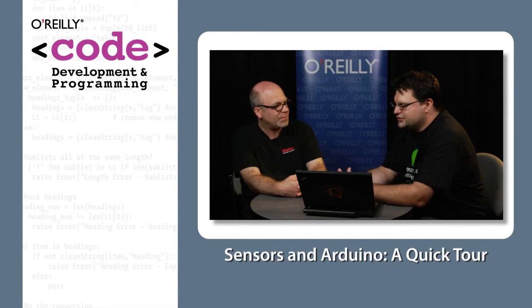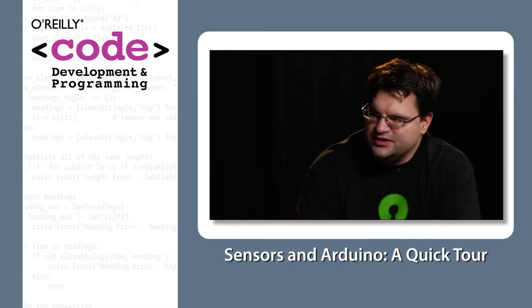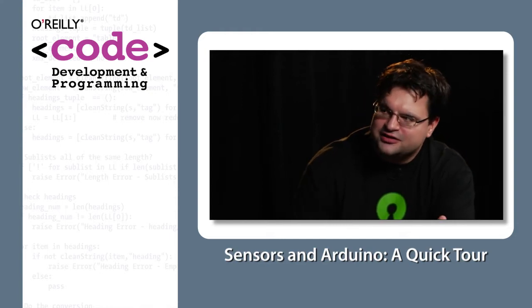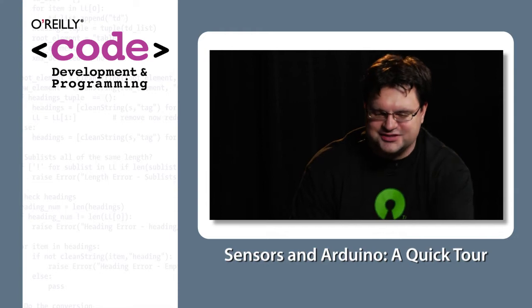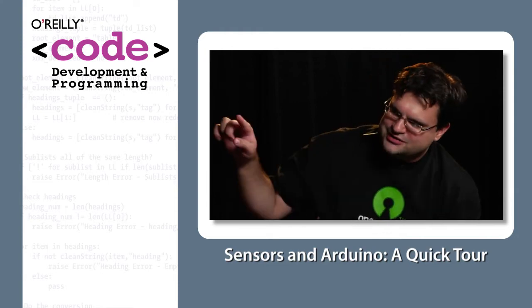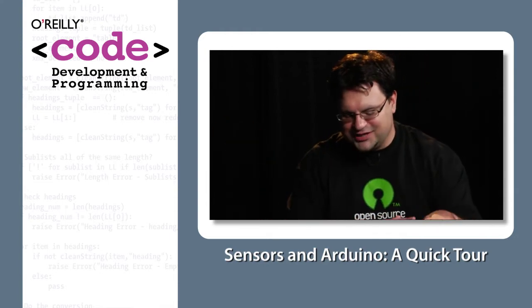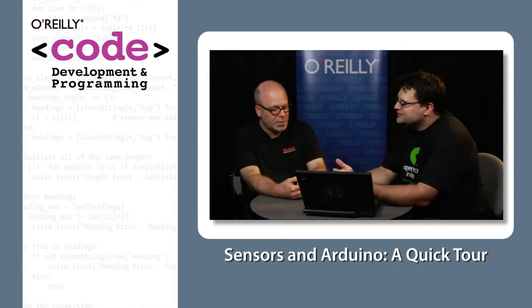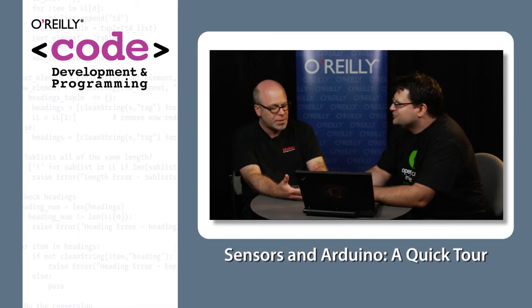That's part of what I've been doing for the book. I have an ADC box so that I can plug the sensor in there and characterize the entire range of the sensor. I can say, well, the behavior of the sensor is that it goes linearly, or that it has a flat area and then it starts responding. So you know what numbers to expect, and then it makes it easier to program against those functions.